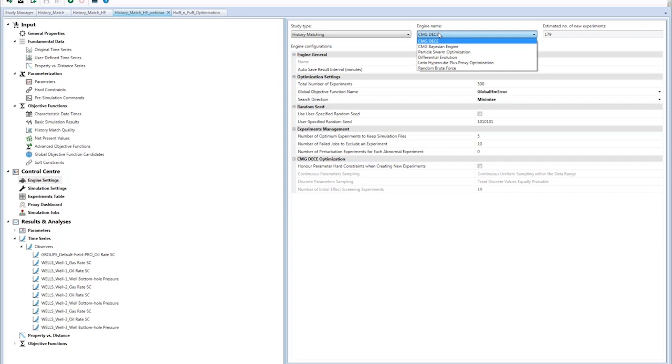The next question is, is there any change in aquifer grids selection option for regional aquifer? I'm not quite getting that question, actually. You can define regional aquifers, and you can assign them to different local regions by specifying the region as grids or as sectors, and then you can parameterize that if there is an uncertainty in the assignment or location of the aquifer.